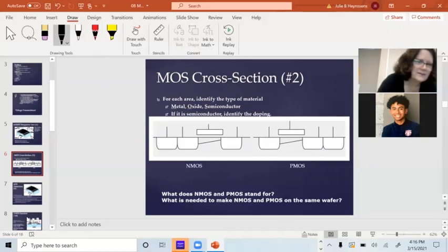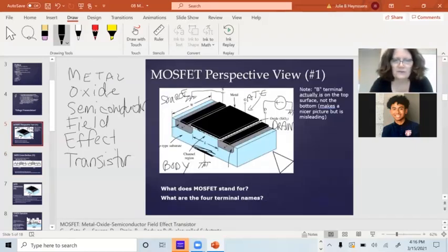Now, this is a picture of what the transistor looks like from the side. Normally, when you're doing VLSI design, you're looking at the top view, looking down at the gate, and you see the different regions of operation, the different metals and the different chemicals you put in. Sometimes they want to see what's going on from the side view, and that's called a cross section, very destructive testing. You actually take the chip and take a saw to it and slice through it and look at this cross section underneath an electron microscope.